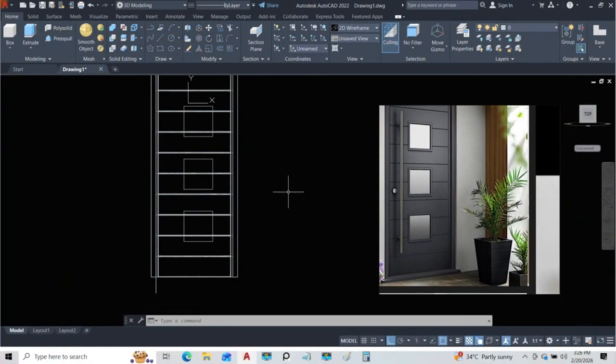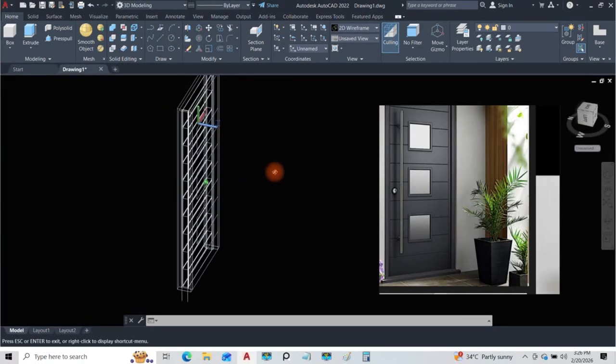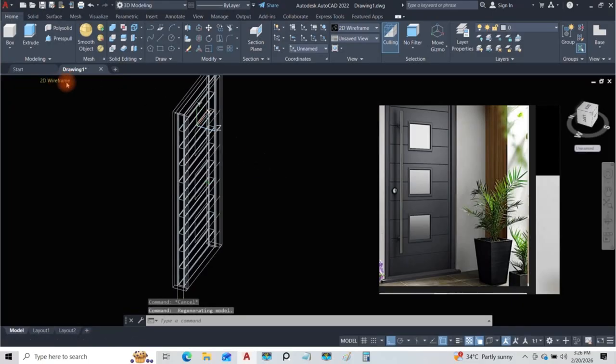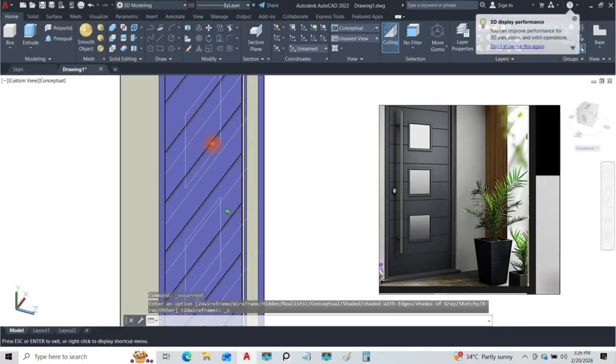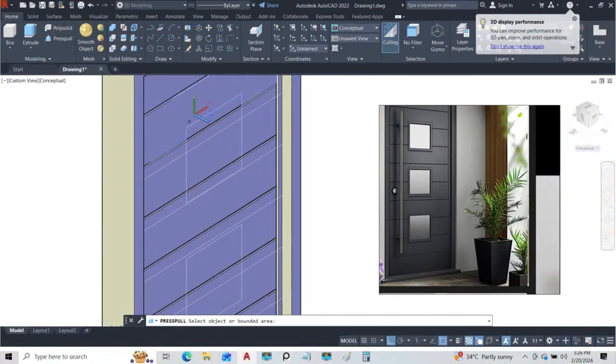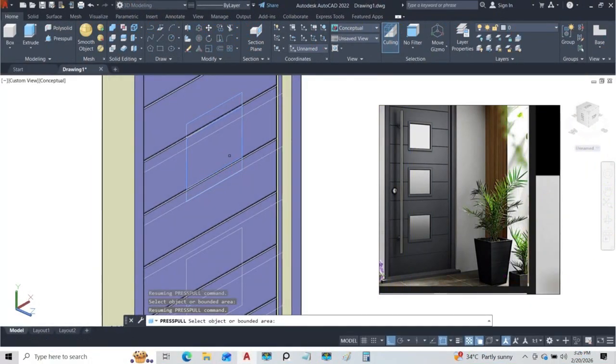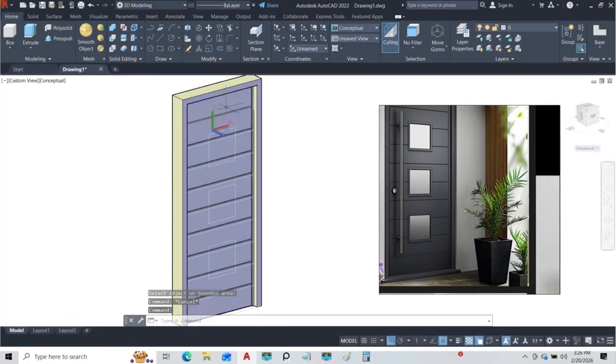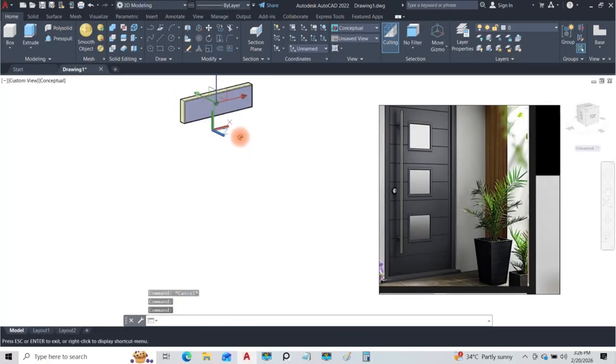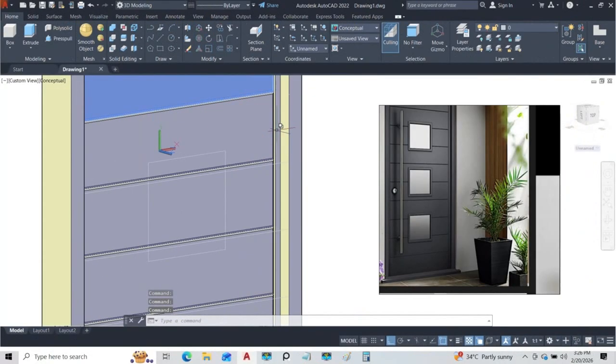just more like cutouts. But now the problem with this is, if you look at it, and let's actually do this here. If you try to do a cutout here, press pull, you see what's happening is it's not picking the whole shape, it's just picking one segment of the shape. So what can we do? We can select all these guys, join them to become one object. That's including this, before we can run this operation.